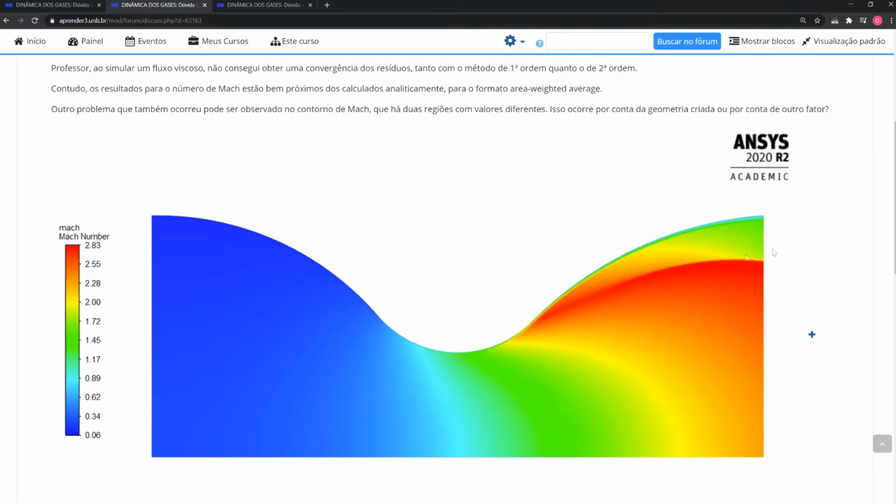It looks like a shockwave, very weak oblique shockwave when flow transits from one region to another. This happens when our nozzle is not isentropic, because I did not design this nozzle to work in isentropic conditions. As you already know from the theory, the isentropic nozzle must be created with some specific method, like method of characteristics. And here in this calculation, method of characteristics has not been used, and flow is not isentropic completely.